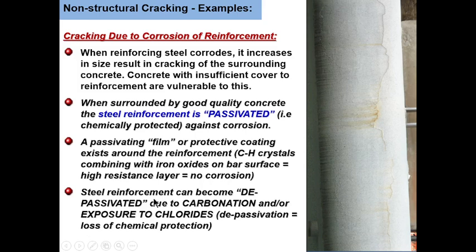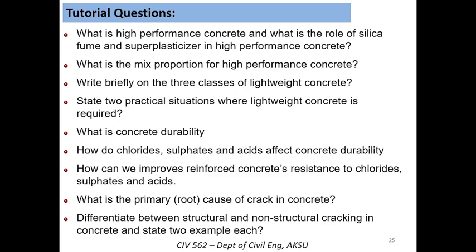Steel reinforcement, however, can be depassivated due to carbonation and or exposure to chloride. When chloride penetrates or carbonation takes place, it can depassivate the reinforcement and expose it to rusting. So there are some tutorial questions here that you can look at and see if you can answer them. The questions are typically based on the lessons on structural concrete design 2, the first part and the second part that we have looked at.